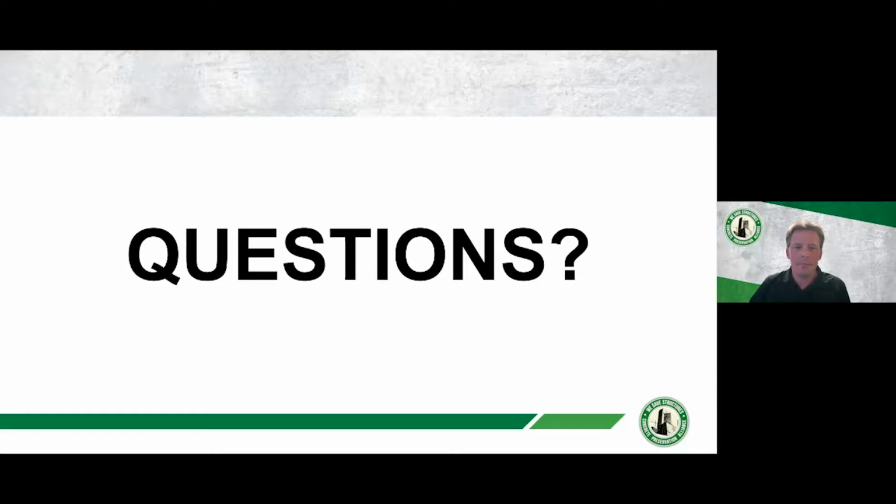Okay, on to the technical questions here. Maybe the zinc metallizing. How long do you expect that to last, like service life wise, in say a coastal environment versus an inland environment? Sarah is asking that question. Okay, so for instance, Yaquina Bay, right? They're getting over 25 years service on that. And that's an impressed current system. An impressed current system is going to run certainly a bit more efficiently. And so 20 to 25 years, not out of the question in that case.